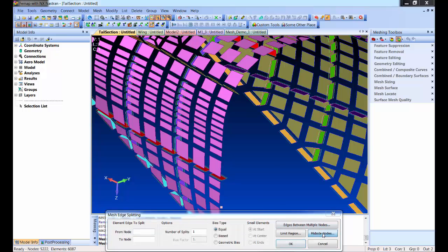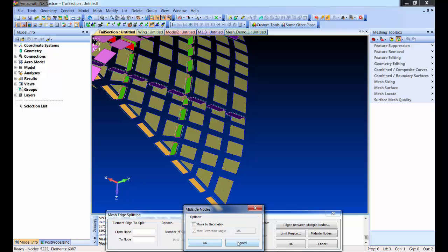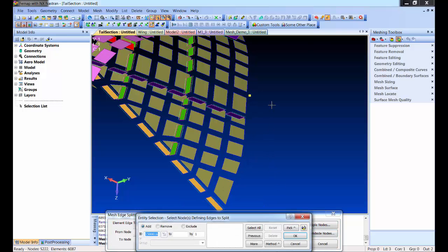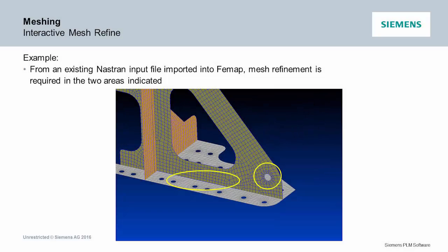And in version 11.3, we added a multi-pick too. So if you were doing multiple nodes, you can now pick multiple. It'll go through and do them at one time. And this does the same thing, splits the beam, properties, pressures, constraints, anything. Just another quick example, T-junctions, whatever's connected is going to stay connected. It gets it all done.